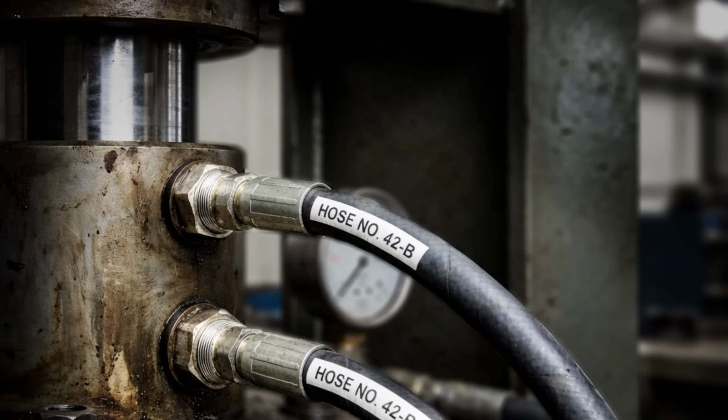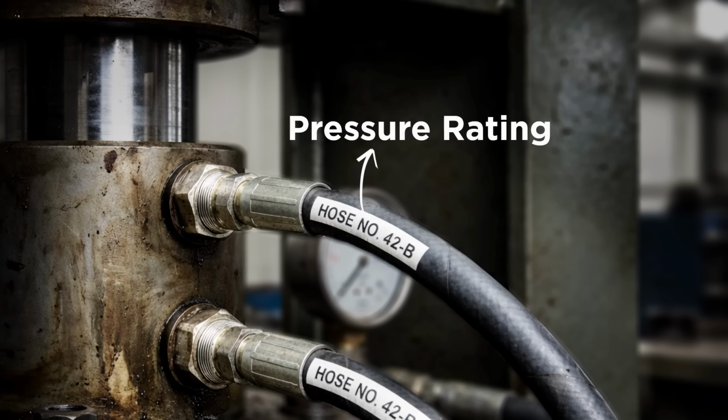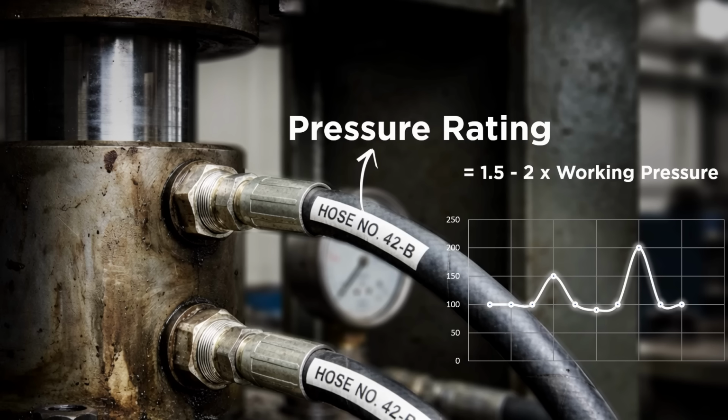Now, whenever we think about selecting the hydraulic hoses, the first thing comes in our mind is pressure rating. We usually say that the hydraulic hoses pressure rating should be at least 1.5 to 2 times the working pressure of the system, so that the hoses can safely transmit oil even under uneven operating conditions, like pressure spikes due to shock loading. But this logic is only true for pressure line.